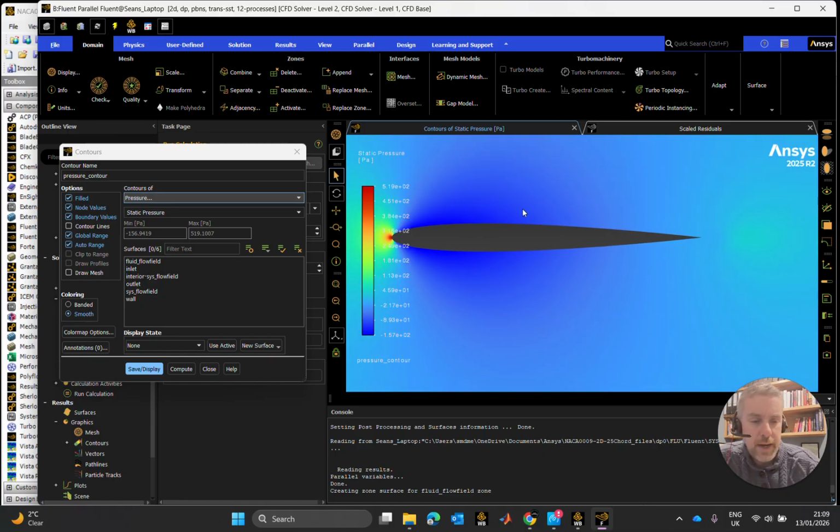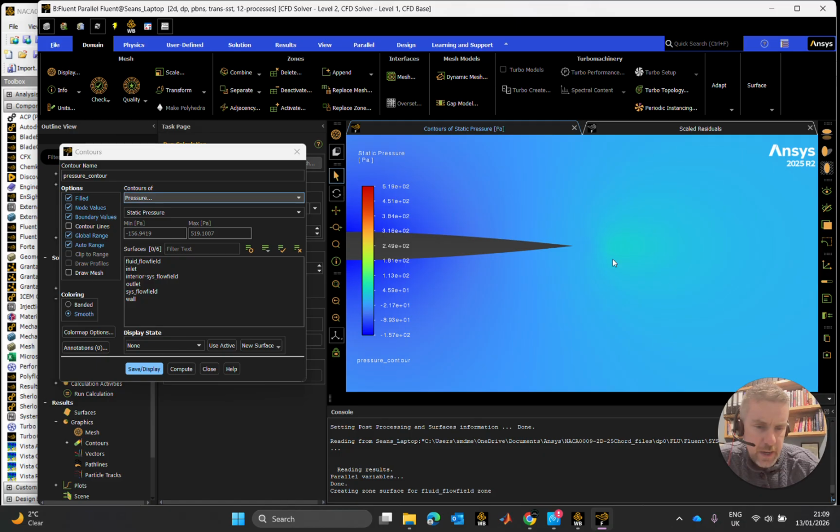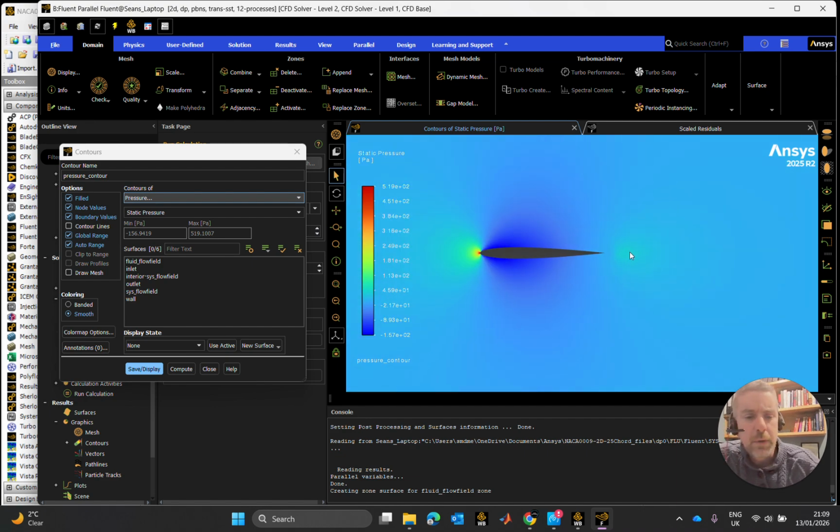Moving back towards the rear of the airfoil, I could see that the pressure slowly started building as it goes more sky blue, and then there is a particularly noticeable greening of the flow field here. Not immediately after the airfoil, but a little bit downstream of it, where I can imagine slipstreams coming from the top and the bottom meeting again, and a little bit of squeezing happening there, which would raise the pressure slightly. But that's only a guess until we give this some further analysis.